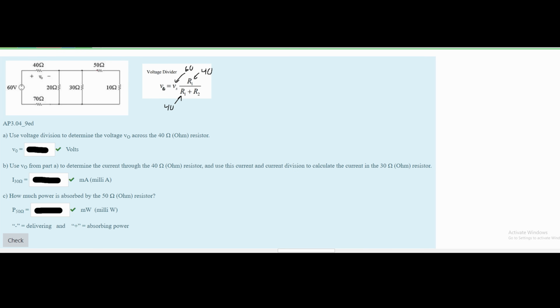So we will get our 50 ohm resistor and our 10 ohm resistor together, and this will make a 60 ohm resistor. Then we can see that this 60 ohm resistor is in parallel with our 30 ohm resistor and our 20 ohm resistor. So we're going to use the resistors in parallel formula. We'll have 1 divided by 20 plus 1 divided by 30 plus 1 divided by 60, all raised to the power of -1. And if we do this, we are going to get 10. So this 10 ohms is going to replace this 20 ohms.